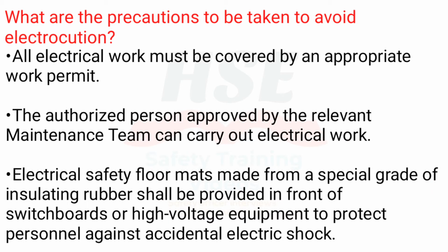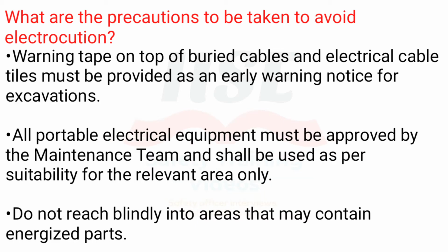What are the precautions to be taken to avoid electrocution? All electrical work must be covered by an appropriate work permit. Only an authorized person approved by the relevant maintenance team can carry out electrical work. Electrical safety floor mats made from a special grade of insulating rubber shall be provided in front of switchboards or high-voltage equipment to protect personnel against accidental electric shock.